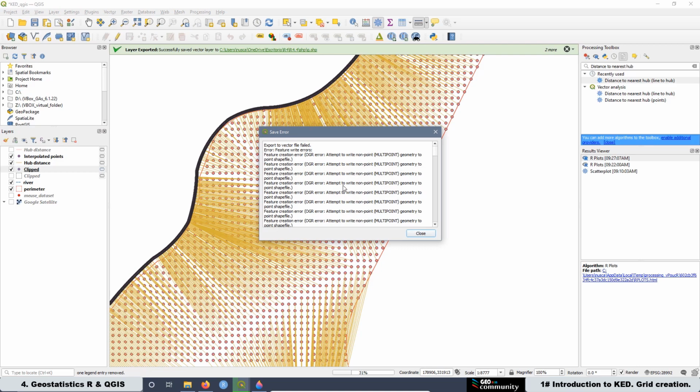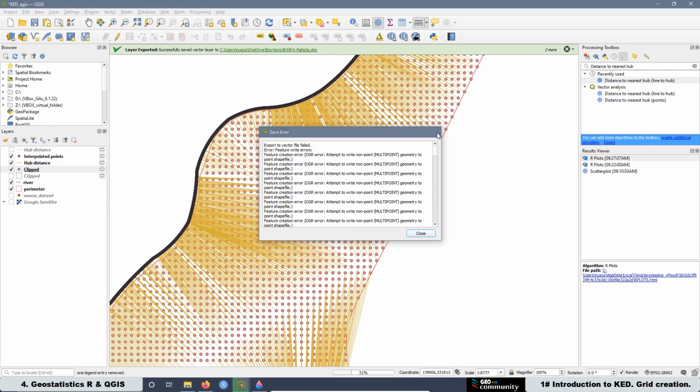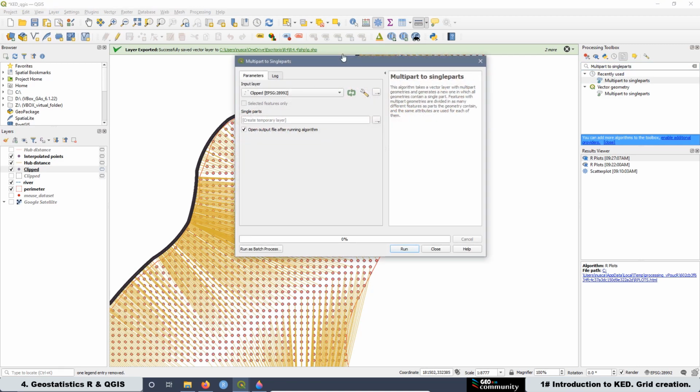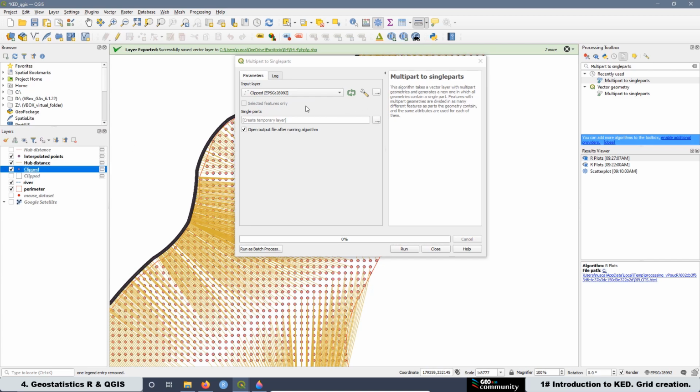Okay, here we have a problem that is saying that we want to save a layer that is multi-point as a point, and it is not allowed, right? Then what we have to do is convert this layer to a point. To do that one, we are going to use the next script. Paste is going to be this one. This one allows us to convert the vector layer to simple points. Then I want to convert this layer, the one I put over here.